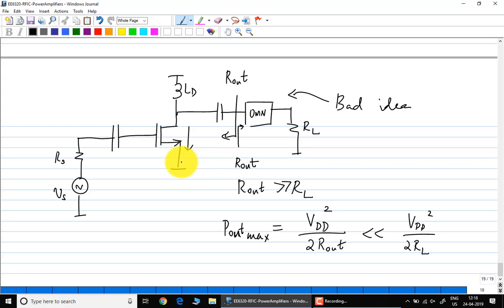How much current do you think that requires? You will require an I bias of about 40 milliamps, signal current of about 40 milliamps. To support an I bias of 40 milliamps, you will need several tens of microns of width. Choosing LD with low Q is difficult if the width of the trace keeps getting larger and larger to meet the current density requirement. It is just much more straightforward to explicitly put a resistor in parallel to ground or VDD. You could put a resistor to VDD like this if you want. I just showed it on the right side as a resistor to ground. That's all.